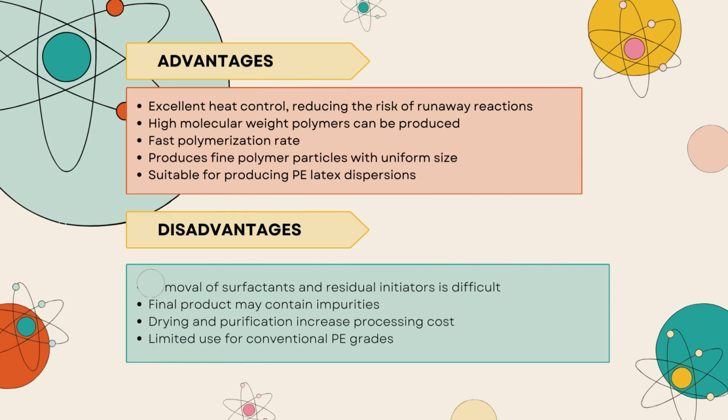But on the disadvantage side, removal of surfactant and residual initiator is difficult. The final product may contain impurities. Drying and purification increase processing costs, and it has limited use for conventional PE grades.